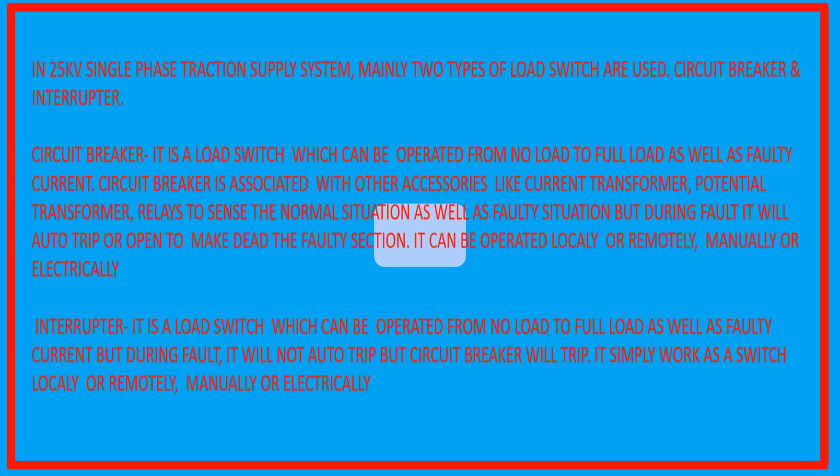Circuit breaker is associated with other accessories like current transformer, potential transformer, and relays to sense the normal situation as well as the faulty situation, but during a fault it will auto trip or open to make the faulty section dead. It can be operated locally or remotely, manually or electrically.